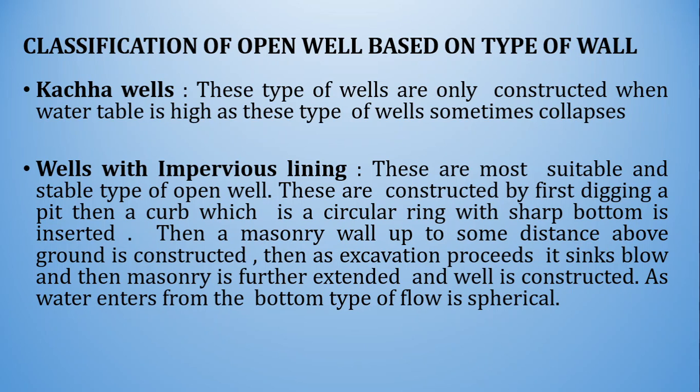the lining purpose. So after casting and curing and having adequate strength, below the curb the excavation is carried out, and since the masonry wall will have adequate self weight, the curb along with the masonry circular wall will sink as and when the excavation proceeds, and the process is continued till you get the water, and further the excavation is stopped as and when the water enters from the bottom.